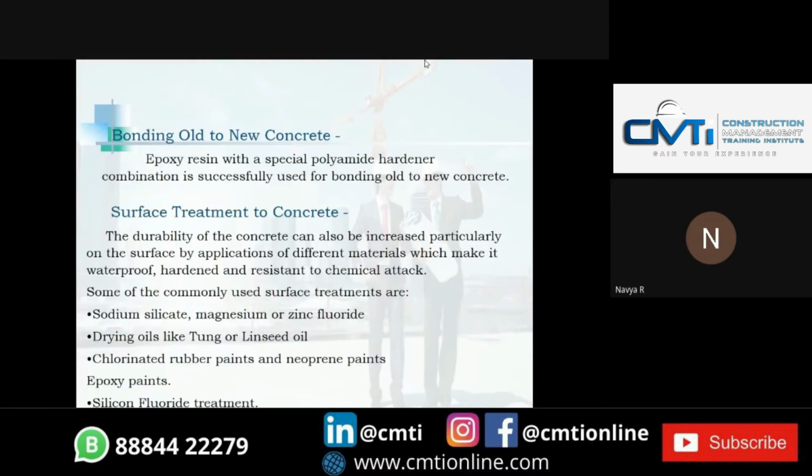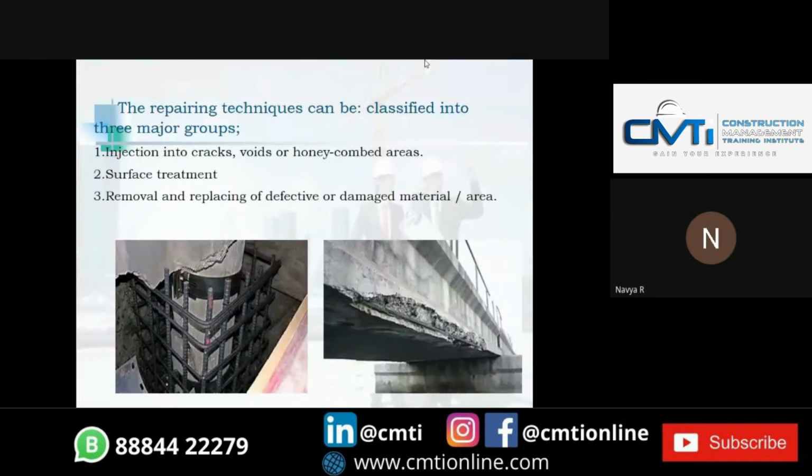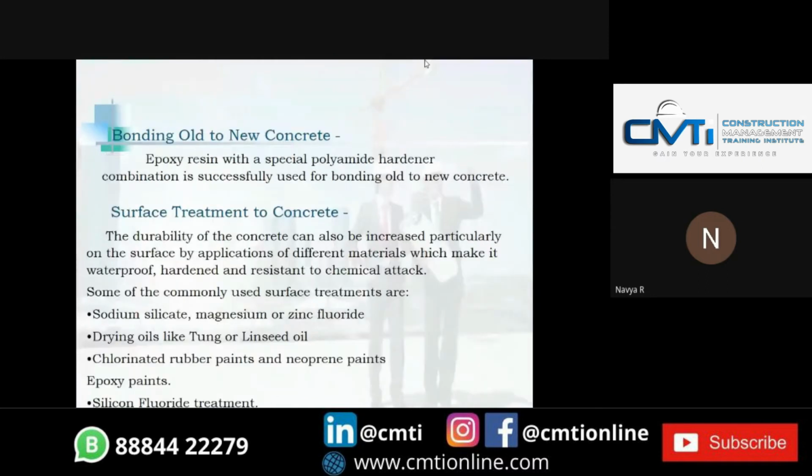And so how do we... this is one topic where bonding old concrete to new concrete. How is the old concrete which is damaged bonded to the new concrete? So epoxy resin with a special polyamide hardener combination is successfully used for bonding old concrete to new concrete.